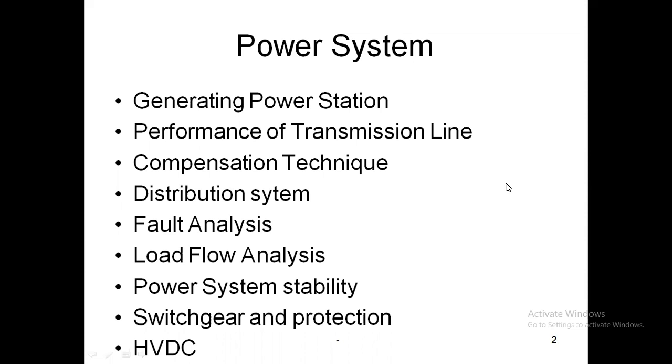Also, because these are very tough calculations if we go with normal network theory, we will introduce another convention by which we can easily do this fault analysis, that is known as the symmetrical component. If we have any kind of unbalanced system, where the phase currents or phase voltages are not balanced, meaning they are not 120 degrees apart, then we will use symmetrical components by which we can easily analyze the unbalanced system. So these symmetrical components will also be introduced in the fault analysis chapter.